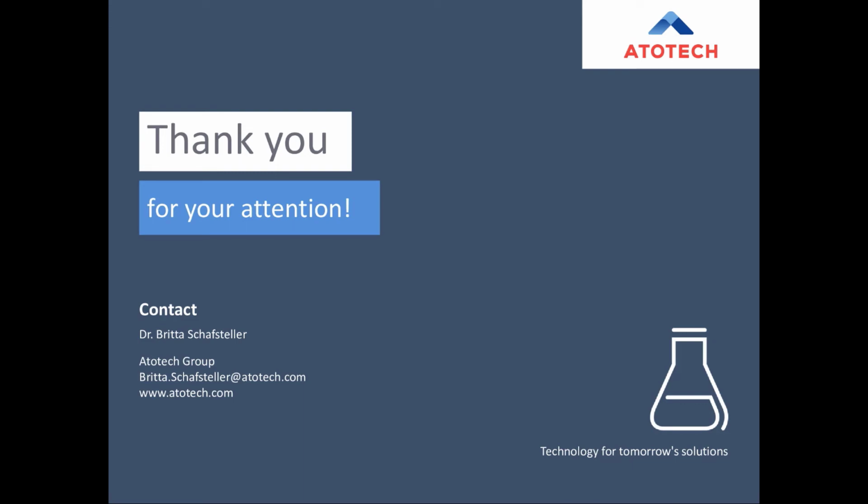Let's say the quick one is done by light microscope, and then the details are checked by SEM. It's a kind of compromise you have to make here. The light microscope is definitely the cheaper and faster method that can be done easily, and where you can easily screen a whole cross section with several PTHs in short time. But your resolution is limited, and if you want to look in more detail, then you really better add some additional SEM investigations.